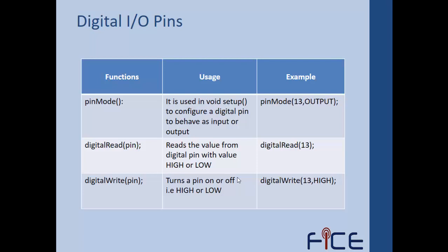This instruction will make pin number 13 an output. Whenever this instruction is executed, pin number 13 will behave as an output pin, meaning you can now write something on pin number 13. What can we write? Only two values, either 0 or 1.